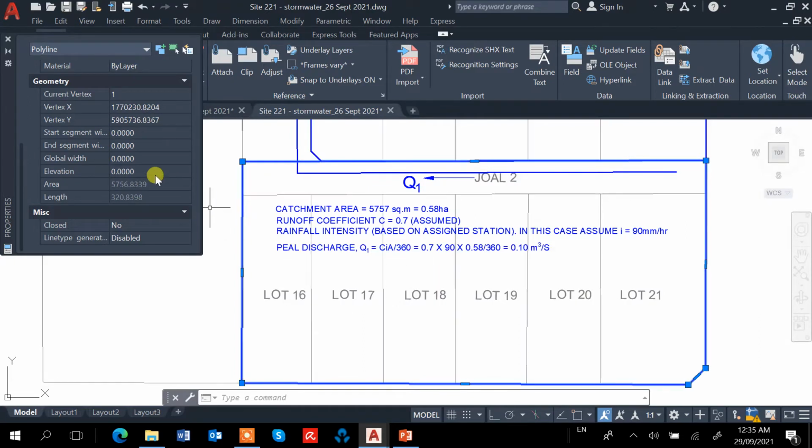The runoff property, this is a built-up area. If the surface is fully paved or covered, with only a little bit of grass verge, the runoff coefficient could go up to 0.9. But I think we have a hybrid.